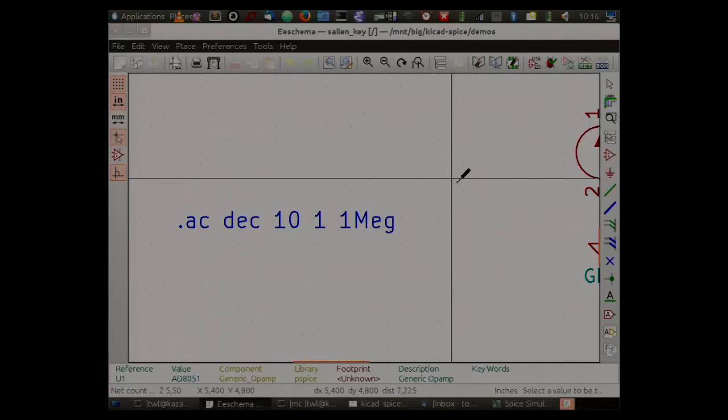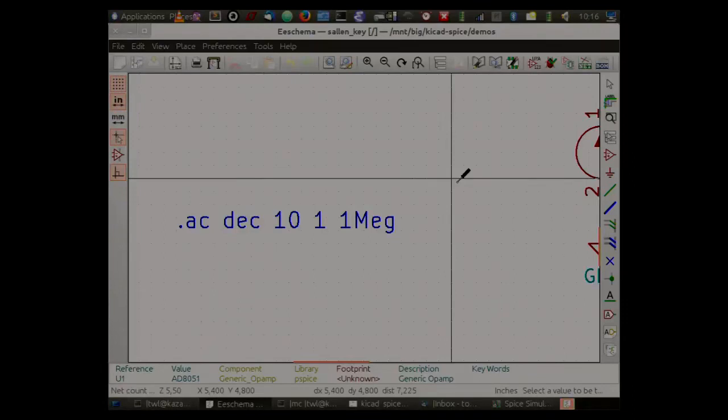The data is extracted basically as tables in the memory, but the netlist is parsed the normal way and passed to the simulator. But the thing is, it's not like you save a file and you load it somewhere. There's an interface for an ngSpice library that allows you to issue the whole netlist using a function provided by the library. Can you repeat that? You did a Python interface over the ngSpice library, and then you're using the Python interface, isn't it?